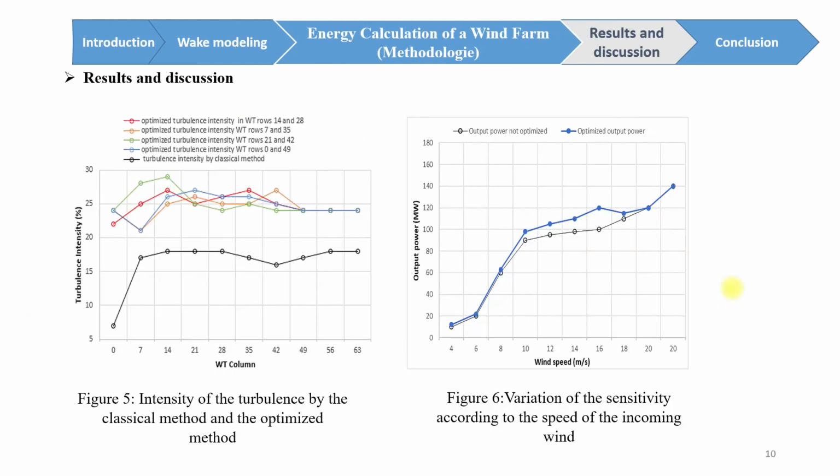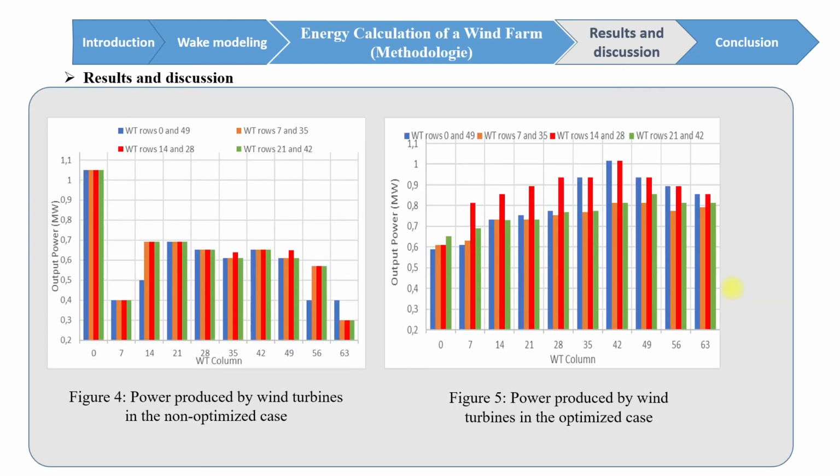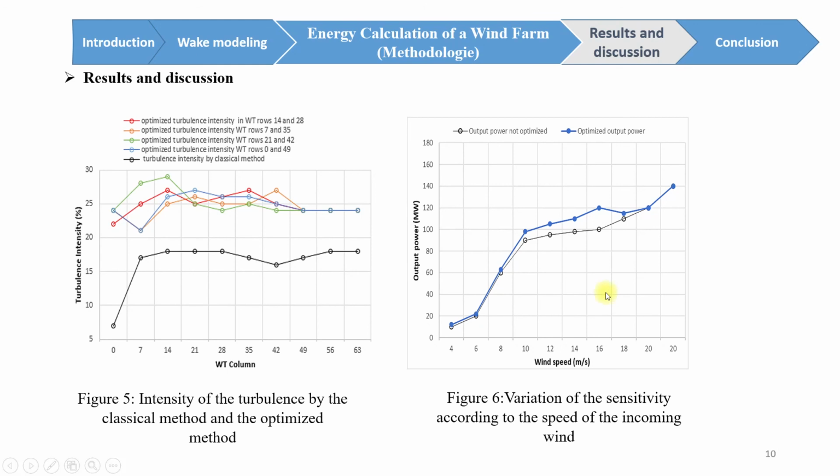Figure number 5 shows that the turbines in column 0 all operate with a negative pitch angle value. Therefore, they have a power output lower than the rated power for the average wind speed. In columns 7, 14, and 21, the last column, the turbines take the value beta equal to 0 degrees for their pitch angle. So they operate at the maximum power.